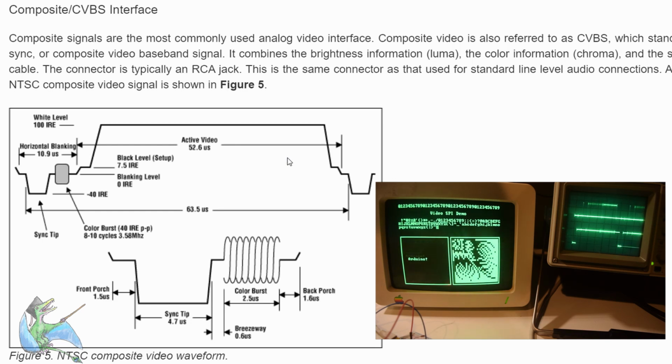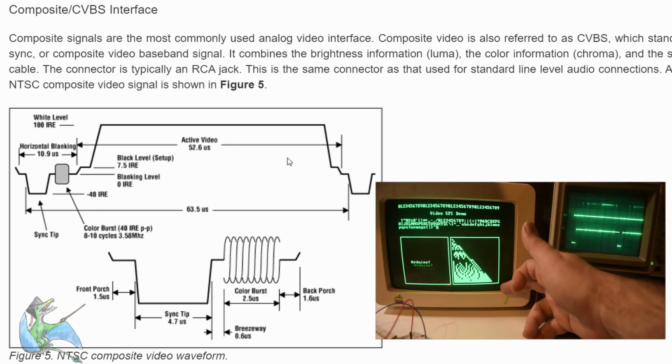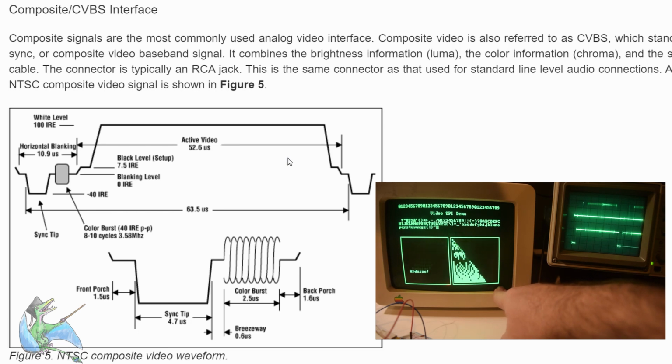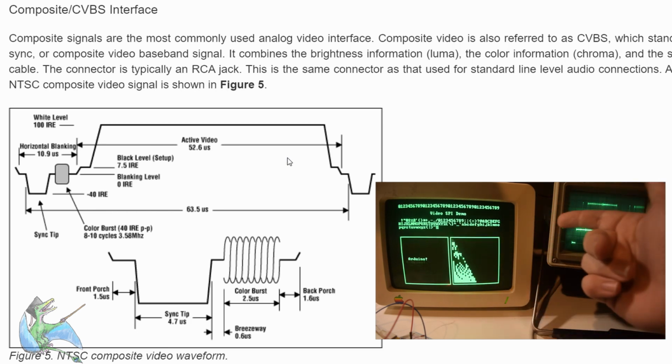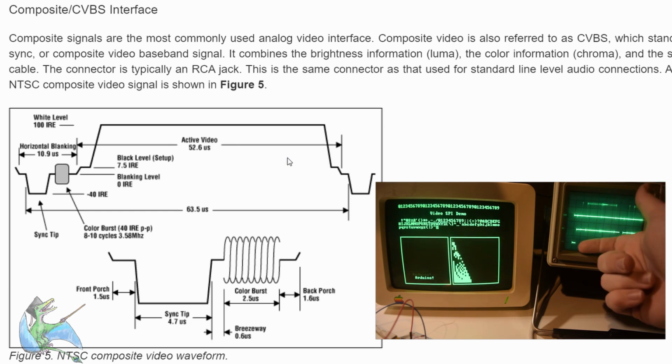Wash and repeat. If you're doing non-interlaced video, which is kind of a hack on NTSC, but it's what most 70s and 80s computers and game consoles did, you get 262 lines, and then you have to send the vertical refresh pulse, which involves basically reversing the polarity of the underlying sync signal.